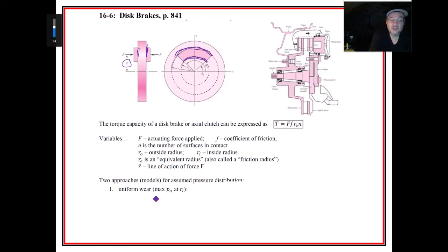But it's also going to be where the maximum pressure is located. So it's not going to be a constant pressure across this whole pad, because you're pushing onto the thing, and the inside radius is where more wear and more pressure are going to happen, right? Over some time, I think the thing would wear out, and then the pressure would probably end up being more and more evenly distributed. But that's not what we're talking about. Not over time. We're talking about in the beginning when it's fresh.